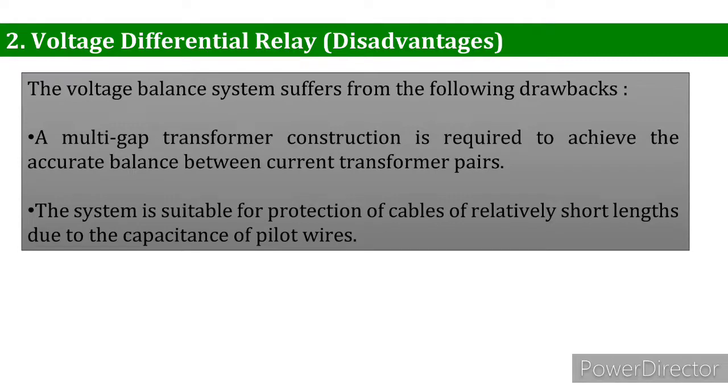Well, on long cables, the charging current may be sufficient to operate the relay even if a perfect balance of the current transformer is attained. In this point, the second disadvantage that we have seen is the capacitance between the cables. As we see, if we talk about transmission lines of long distance, between two different cables,